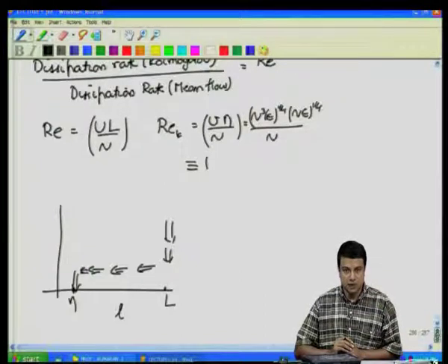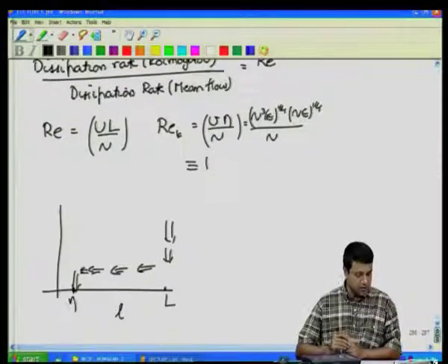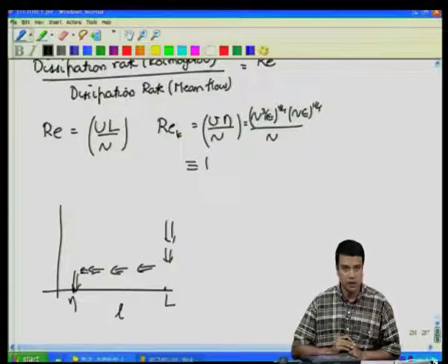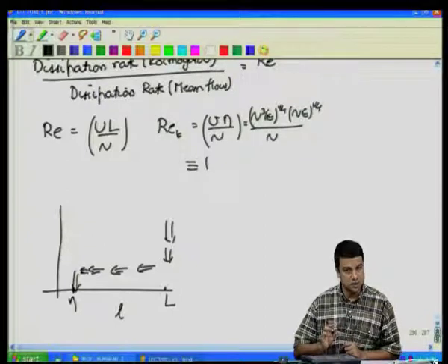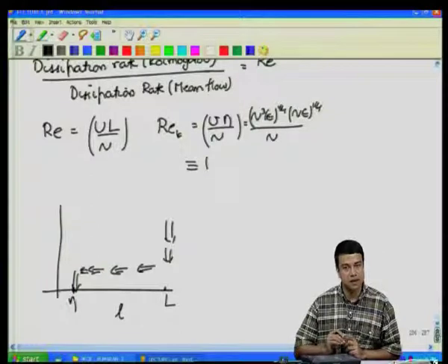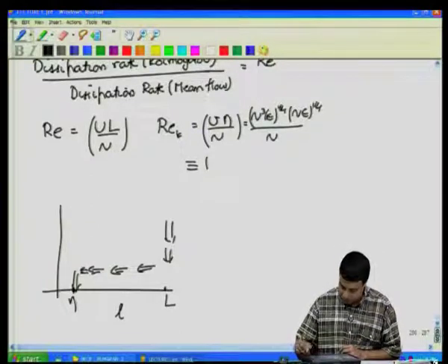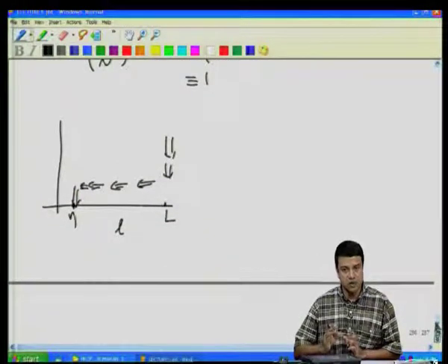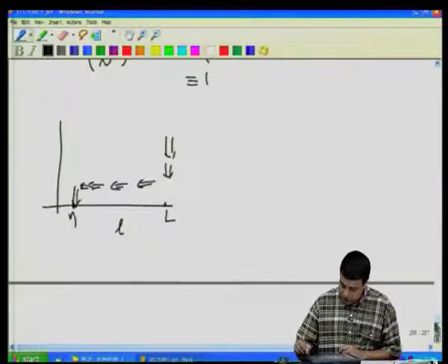There are other things that you can say about this kind of an energy transfer. The one thing is of course that energy is getting transferred from the large scale flow down to the small scale flow. We got the small scale just on the basis that at this smallest scale, the velocity, length and time scales themselves do not depend upon the large scales, but only upon the rate of dissipation of energy and the kinematic viscosity. One can infer how the amount of energy in these flows varies. It is called the energy spectrum.